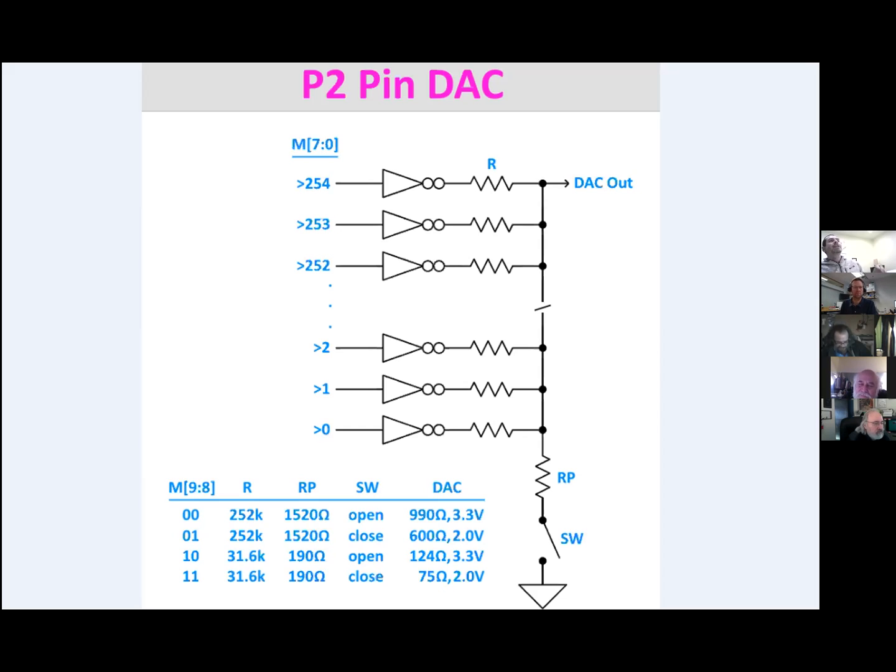And so, see, this is so simple. If you were to try to put any kind of analog feedback loop in there, some kind of op-amp, you'd destroy its quality. This is so dumb and simple. It just works. And you see where we have all these values on the left? Those are actually flip-flops. So all the decoding is done beforehand by flip-flops, so that when the clock rises, all of these update in absolute parallel time.